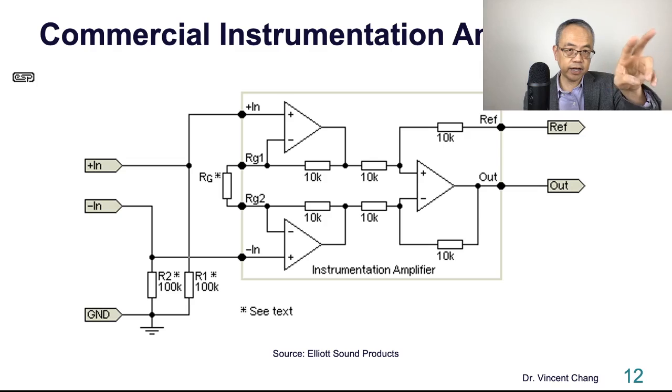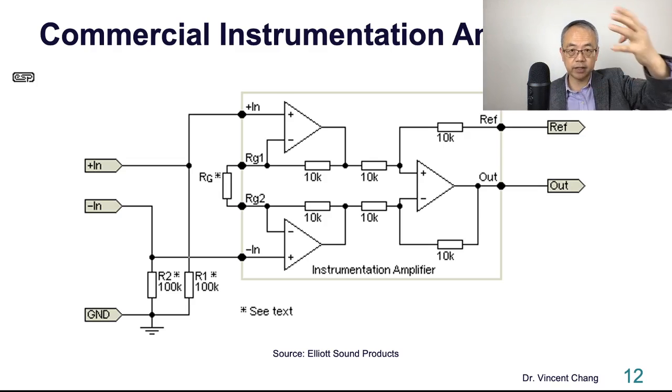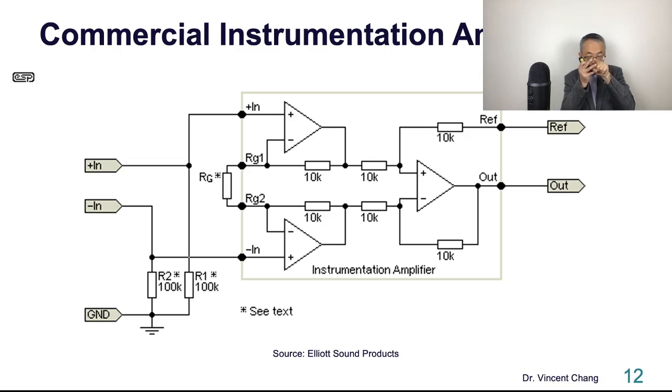See the 10 kilo ohm, you have to pay attention. This is different from the previous one, kind of flipped. Negative feedback is on the bottom. So the ratio, the relationship, differential. And then the RB, which is 10K in this case, is on-chip. But there's the off-chip resistor called RG, associated with the RA in the previous slide.